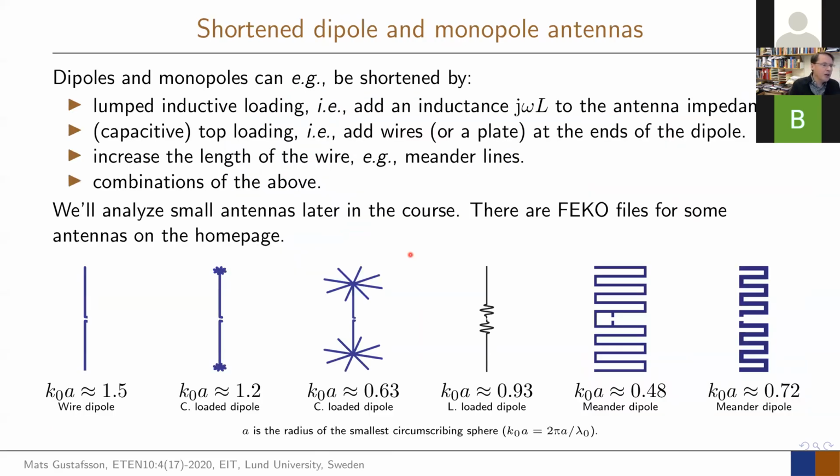Okay, so that was one way of now making our dipole antenna shorter. And we gained a factor of 2. So if you think you would make this Warsaw Tower, okay, you do a monopole instead of a dipole. It's not exactly what they were doing, but you gain a factor of 2 then, and you could say, I can make it like 300 meters instead of 600 meters. It's still ridiculously long.